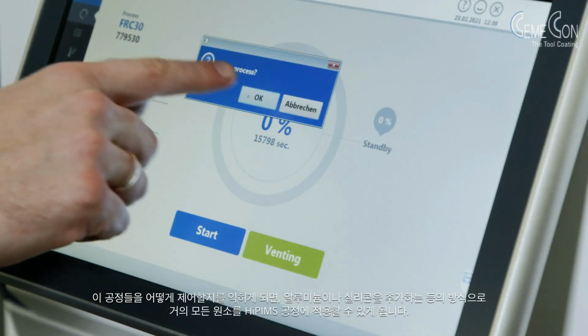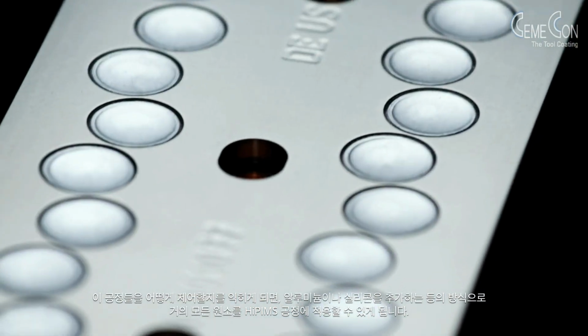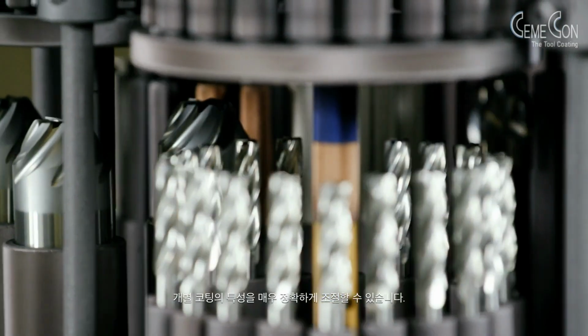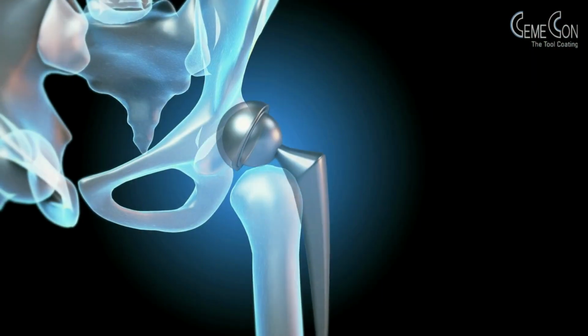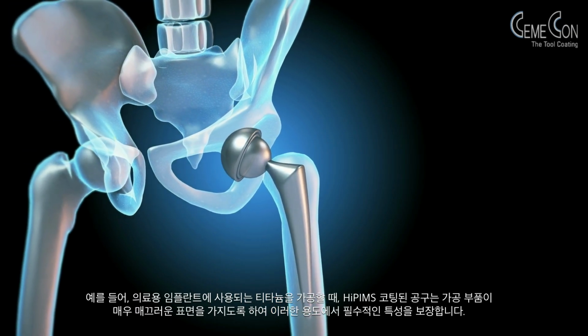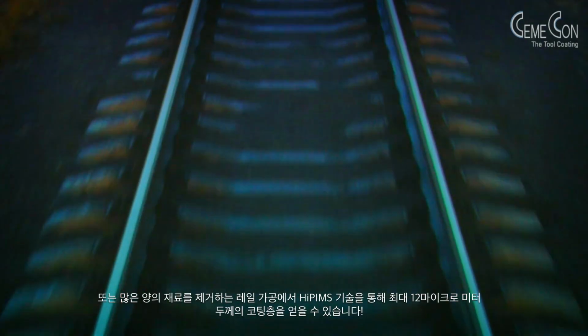Once you have mastered how to control these processes, almost any element can be used with HiPIMS, for example, by adding aluminium and/or silicon. And this means the possibilities for coating are nearly infinite. You can control the properties of the individual coatings precisely. And, in turn, you can optimize the properties of very different cutting tools. When titanium is machined, for example, for medical implants, HiPIMS-coated tools ensure that the machined parts have very smooth surfaces, an essential property in such applications. Or when rails are machined, where a lot of material has to be removed, the HiPIMS technology delivers layer thicknesses of up to 12 microns.